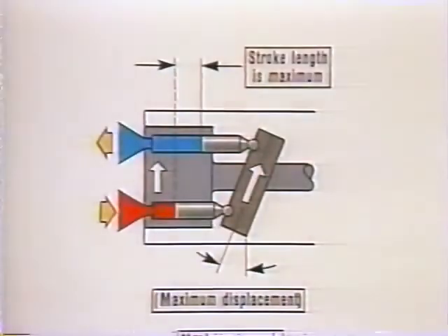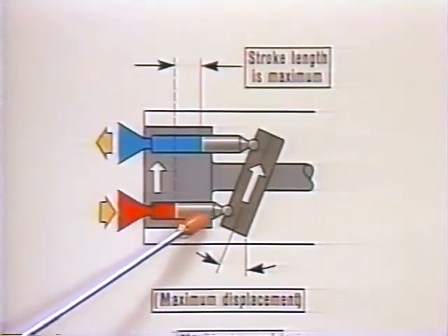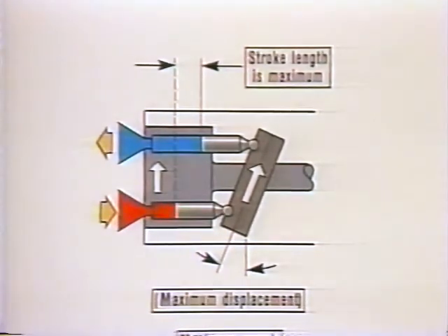Let's switch over now to a study of piston motors. Because of their construction, piston-type motors will usually allow us to operate at higher pressures and speeds than comparable vane or gear units. Here's a simple view of the inside of an inline piston motor. Oil directed into this port gives us a force in this direction. Part of that resultant force gives us a torque for rotation.